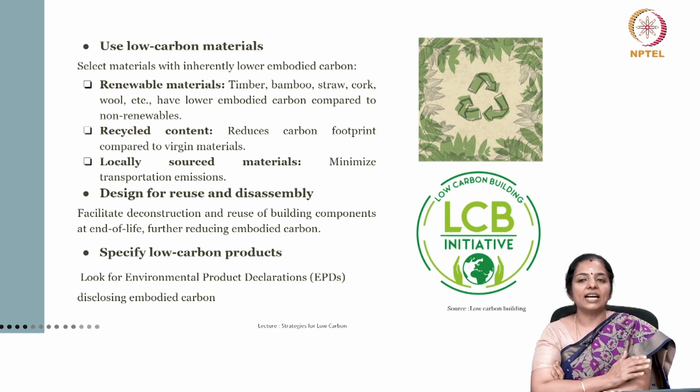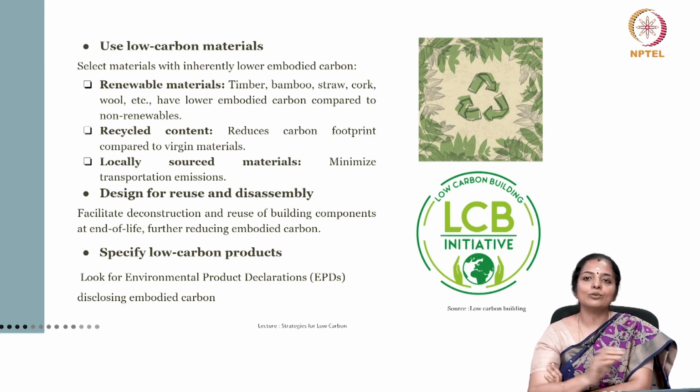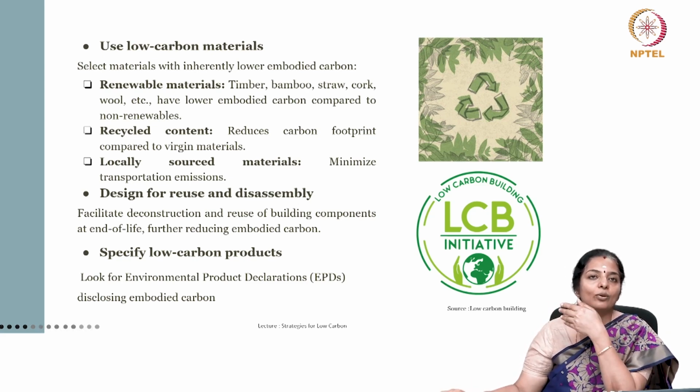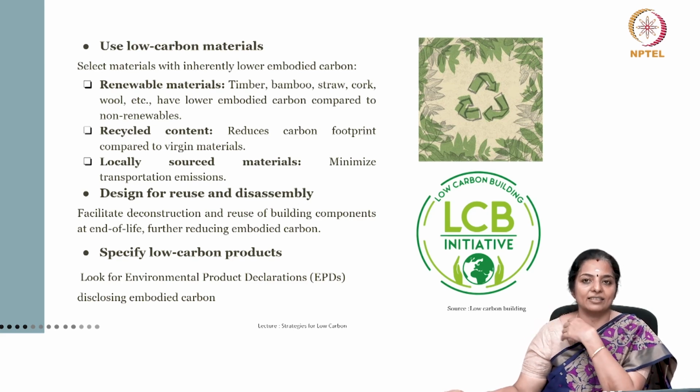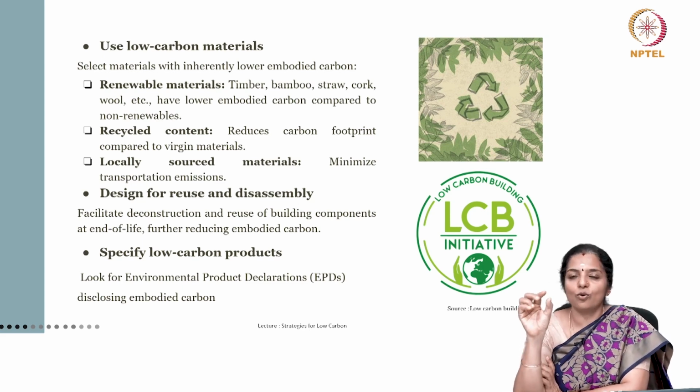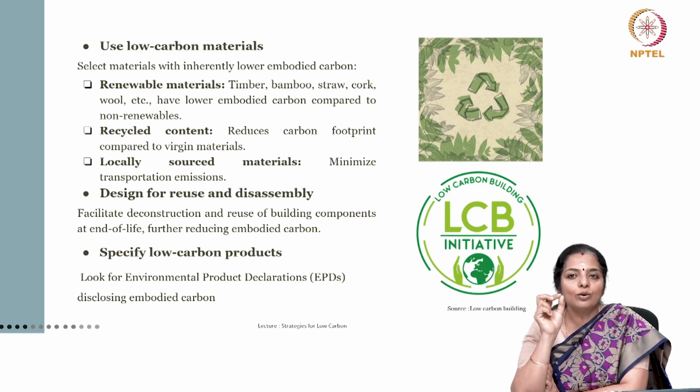Now, all this and the specification of low to zero carbon materials and sequestered carbon, including the design for carbon sequestering sites and the use of carbon sequestering materials, will lead to use of low carbon materials. So, how do you actually know when you go to a place and you now want a low carbon material? How do you do that? First is see if it has renewable material. How will you see? So, look for environmental product declarations,